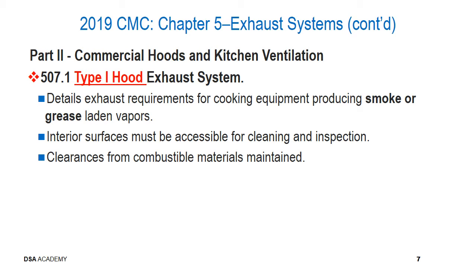The interior surfaces of these types of ductwork that are used to convey any type of grease-laden vapors or smoke have got to remain accessible for cleaning and inspection. Cleaning is required on a periodic schedule to keep the fire hazard down, and inspection of the functioning of the duct itself has got to be done periodically and on a consistent basis. These types of ducts must obviously maintain clearances from any type of combustible materials.